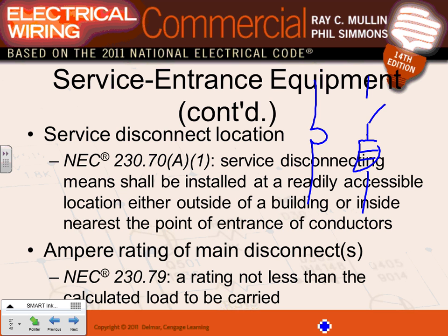These two are called service disconnect means. If you have a breaker, you can disconnect and protect the system. If you have a disconnect like this, you can disconnect with this and protect with the fuse. So these two are equivalent to a circuit breaker. Can I have a thumbs up, Chad? Okay, so we got that one.